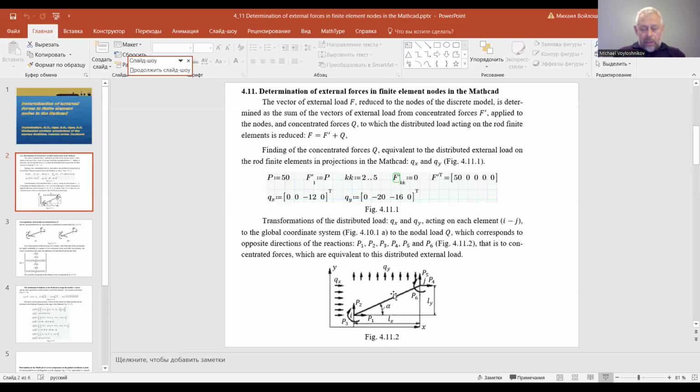So we have to multiply the magnitude of the vertical distributed force by the projection of the inclined element of the mechanical system, in the general scheme, general for any elements of the mechanical system, not only for the considered system. So multiply the distributed load by the horizontal component along the abscissa axis.